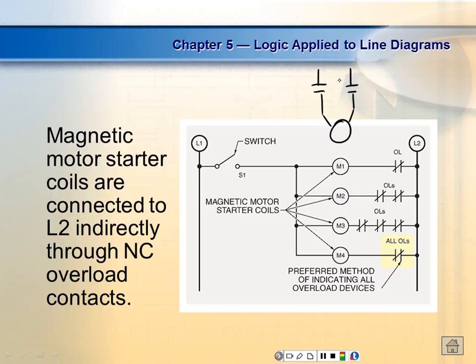What we like to do is break both lines, because that way, if this line breaks and this guy stays open, then that motor is electrically hot. You can get your butt zapped by getting the ground. Unfortunately, if I was in a place called U.S. Steel, I would have to double break a 240 volt motor. Residential lives under their own rules. So you get by a lot in residential. The National Electrical Code lets you get by a lot in residential that we don't.